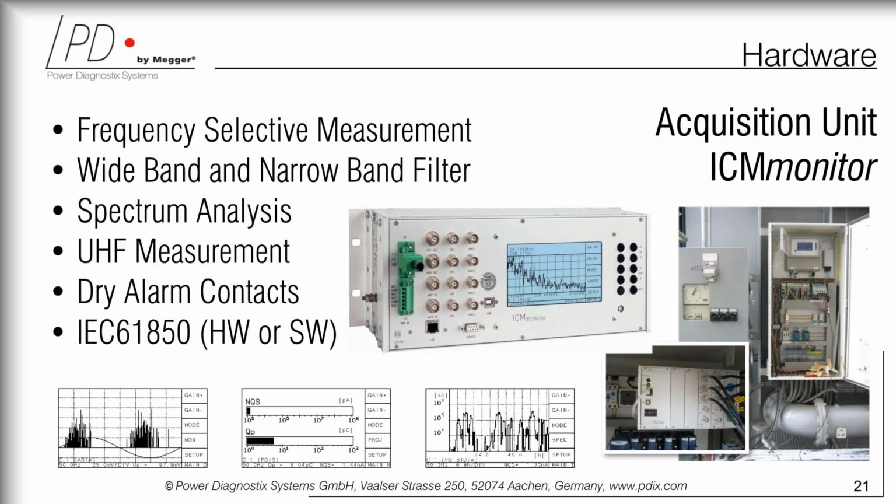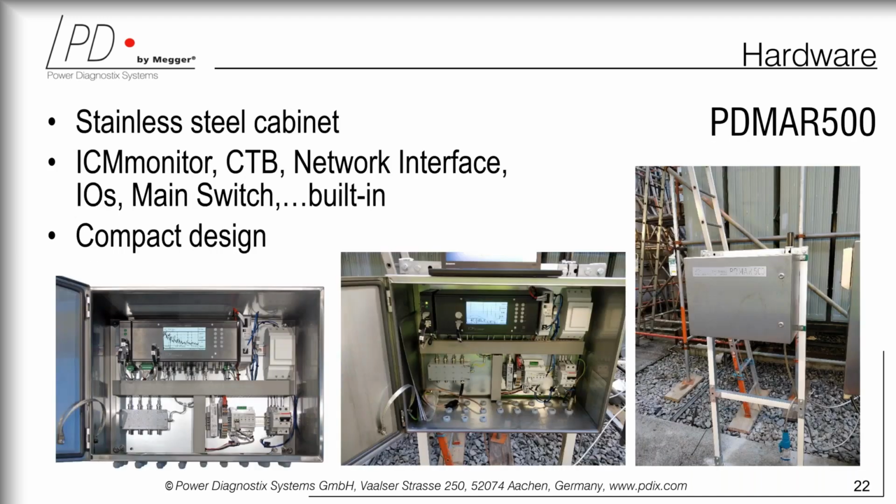In this case, you can see this picture, another type of case which has of course a screen, has a certain number of channels, has the LAN, and of course the binary annunciation, and has also a comm interface, RS232 interface. These are other examples where we are using steel cabinets. They have also a very nice marine name, TDMR 500. We've even installed them on boats, on other things, but for transformers, these are typical ways of deploying the device.